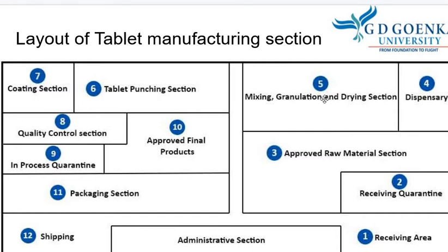End point of granulation is determined by LOD, so IR moisture balance. Drying section, fluid bed dryer, wherein the end point for drying of the granules, LOD, is evaluated, again using an IR moisture balance which is present in the quality control section. Tablets punching section, here also the samples of tablets are sent to QC for evaluating the disintegration time, friability, hardness,